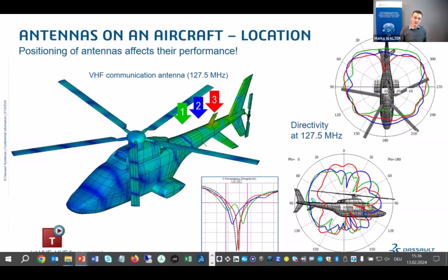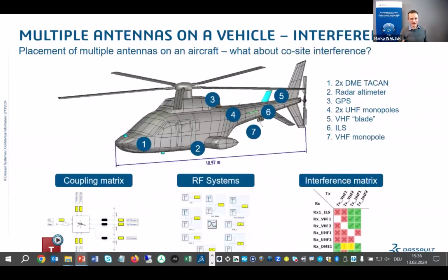And of course, we even have the matching bandwidth, which reduces because we're moving the antenna closer to the tail fin. So the point is understanding how the position of an antenna in its larger environment influences its performance allows you to make decisions about how to place it. Of course, there's one more thing, a minor technicality.